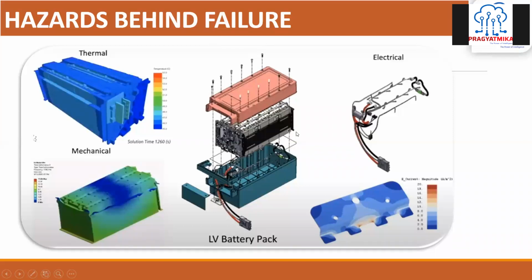But when we talk about safety and why battery packs fail, there are 2-3 things that we always have to consider, specifically in the design phase. The batteries should have a thermal design, a mechanical design, and an electrical design. Under thermal design comes the question of what temperature levels the battery packs reach. So what is the exact thermal management method that you have to apply? Do you have provisions for an active cooling system or a passive cooling system?